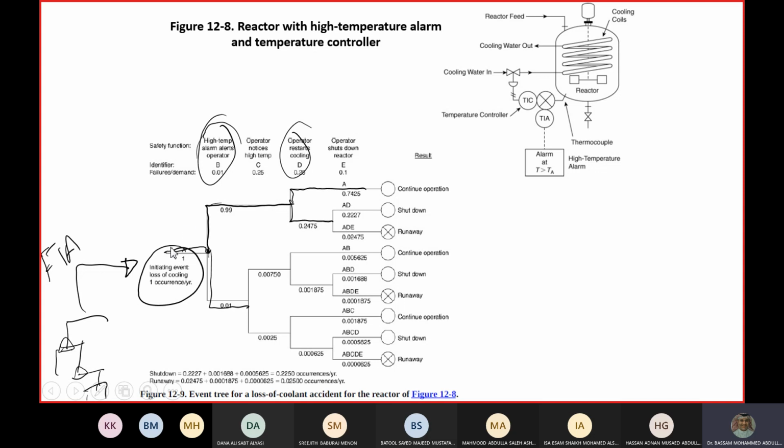So this thing here is an example of how you're trying to calculate using the event tree analysis, where you're going to decide to continue operation or to shut down the system or to do whatever you want to do, depending on the reliability information or the probability information that is stated here. Now, these values, how did we calculate these values? I think you already have taken this. I explained that last time. But this is how it goes. I'll say it very quickly again.